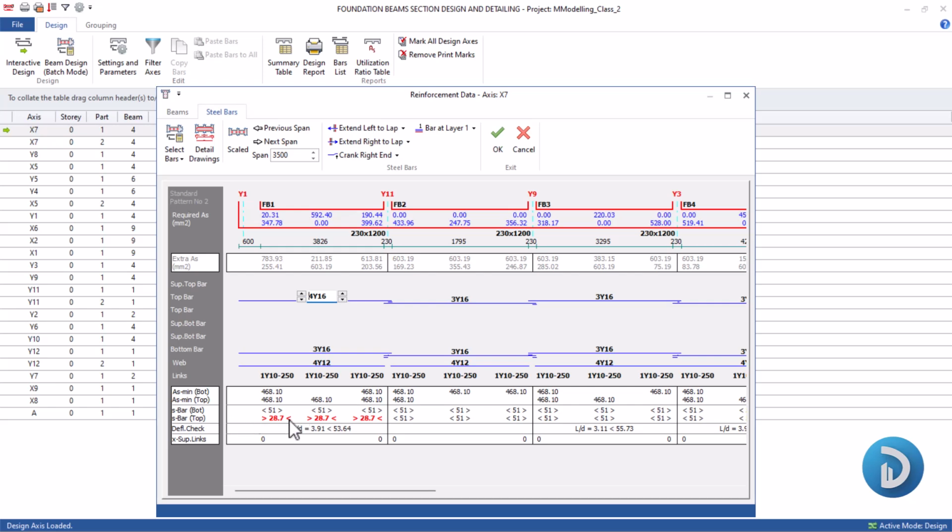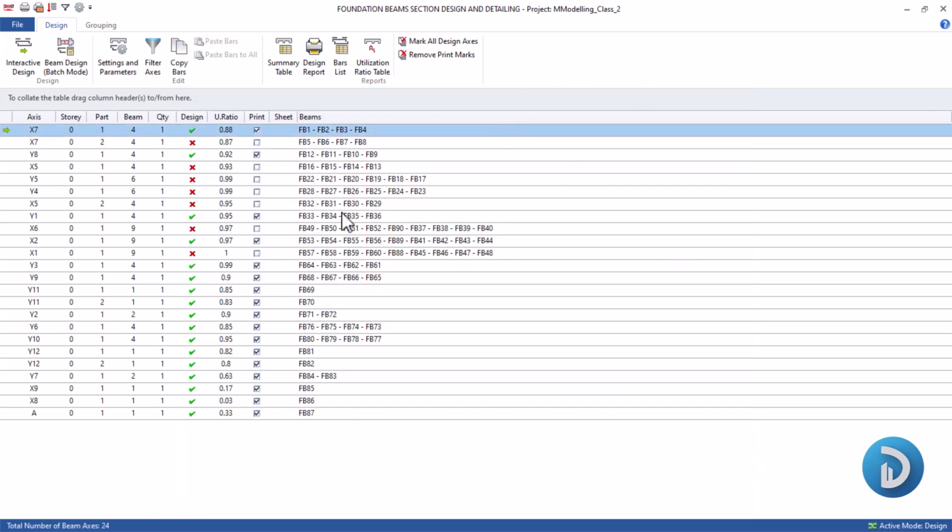All right, so the maximum aggregate size you can use in constructing this beam should not be anything greater than 28 millimeter. So we are actually very safe because the average diameter of our coarse aggregate is 20 millimeter. So we'll click OK. To learn more about that aspect, you can go to our previous videos on beam analysis and design, and you will see a detailed approach on how you can calculate each of those values.